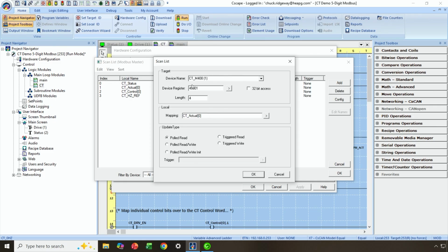Now, intermingled with these parameter numbers, you're going to find there's some 32-bit parameters in here. But remember, we're just going to be reading the lower 16 bits of those parameters and storing the lower 16 bits of those parameters in the variable array I've detailed here, okay? Because the data values that those parameters will have are going to fit easily within 16 bits, this is going to work fine, okay?